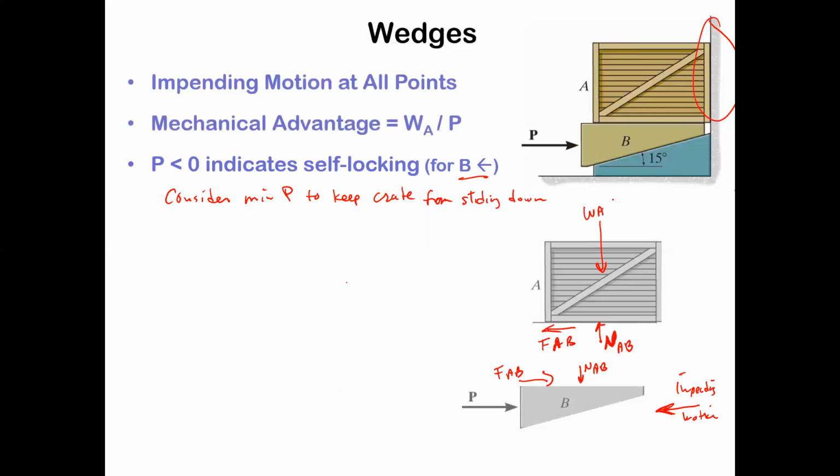Another force acting at A? Yeah, there's going to be a normal force coming from the wall. If we're pushing at it with P, the normal force is going to be pushing back to keep it from going into the wall, right? We're going to call this N_A. Another force acting on the crate? There's one more. Friction from the wall, which way is it going? Up. It's trying to keep the crate from sliding down, right?